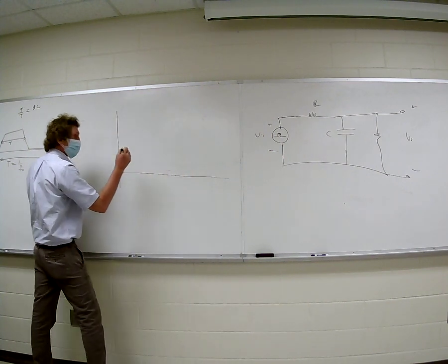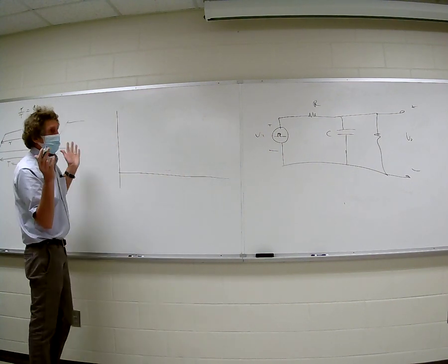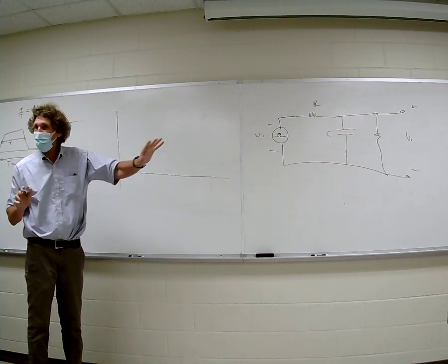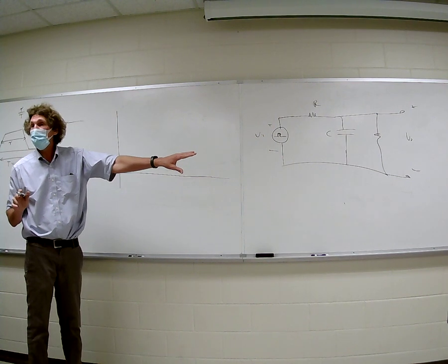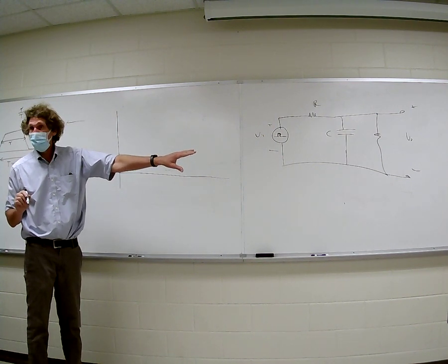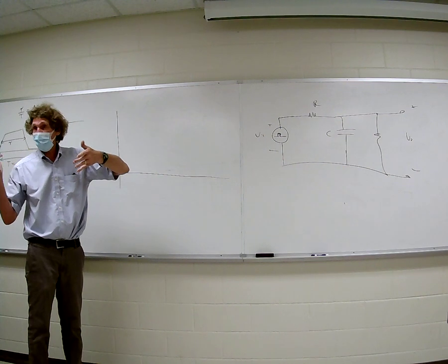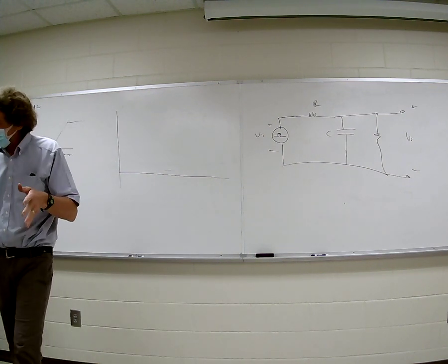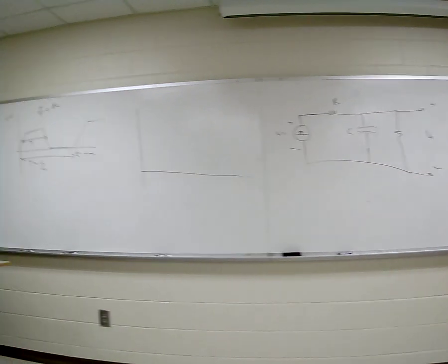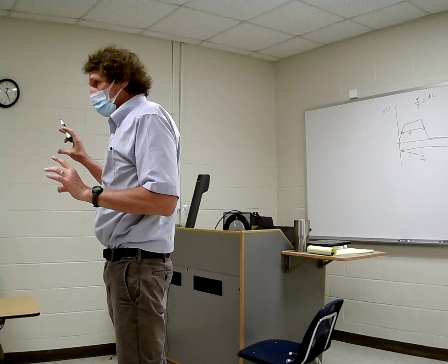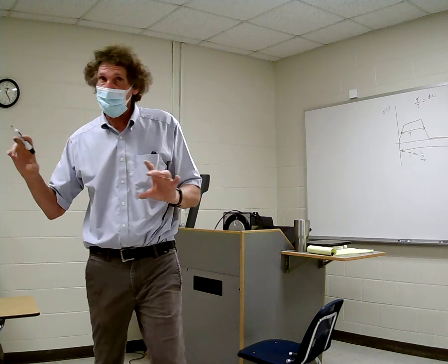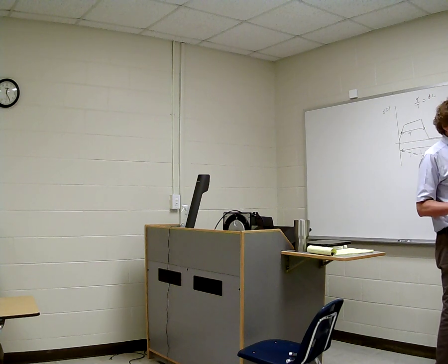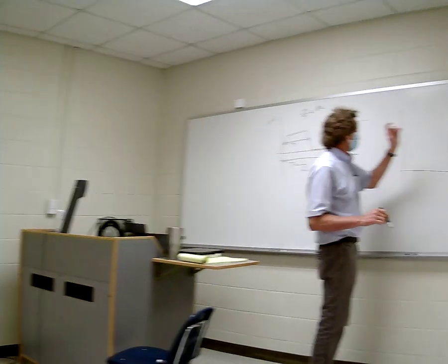First we sketch the input. Or we could, I'll tell you what, we'll get the output at 5 F naught, because we've already got the capacitor. It's a 20 dB reduction in input signal, right? That would cause that, but it doesn't say anything about the waveform, right? Whatever the input signal is, if you're at 50 megahertz and you put that capacitor in, then the input signal will be reduced by 20 dB. You all follow me? Doesn't matter what the input is at that frequency. Now I want the actual output at the fifth harmonic based on this waveform.